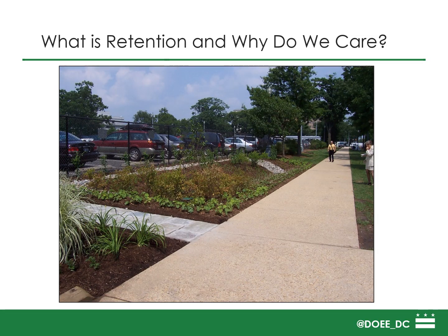To understand the stormwater management program in DC, we first need to understand what retention is and why we care about it. Retention refers to capturing and storing stormwater runoff over the long term. The advantage of capturing and storing this runoff is that it prevents any of the pollution that runoff is carrying from being transported further down into any receiving water body.